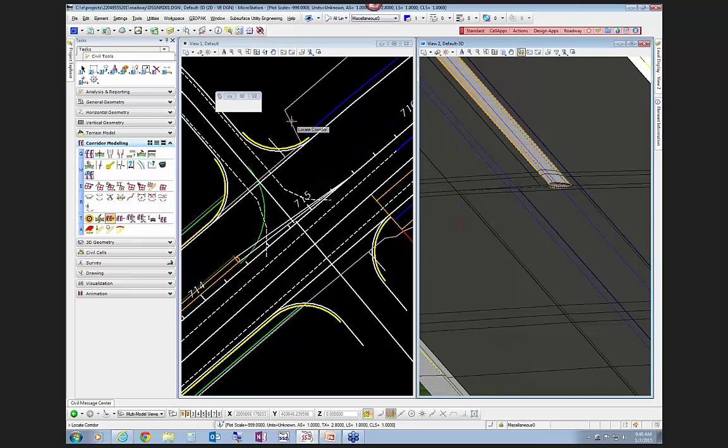I'm going to select these two lines, and they were drawn in as pavement slope breaks. And then I'll reset, and it should process. We may have to set it to the design stage in order for it to use the external references once it's done processing. But you'll see that then basically the crossover will behave like the traffic separator as far as sloping up.